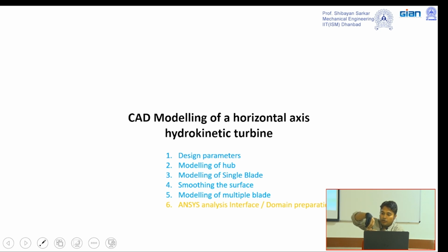So whenever fluid comes, this particular turbine will be rotating like this. Whenever fluid comes, it will have a thrust, so always it will have a tendency like this. So there will be unbalanced thrust on this particular bearing. So there is always a failure tendency or misalignment tendency, or it creates vibration in this particular domain if the strength of this part is not that strong. So that is the main problem if you are using a vertical axis turbine.